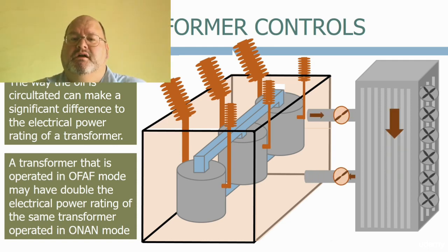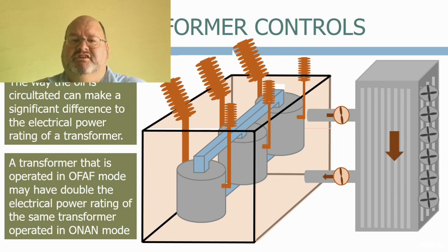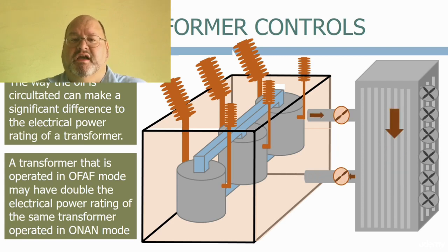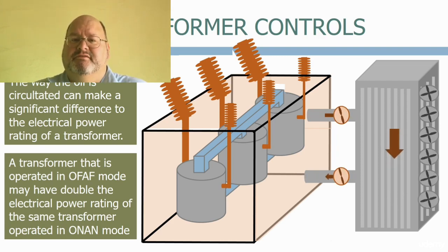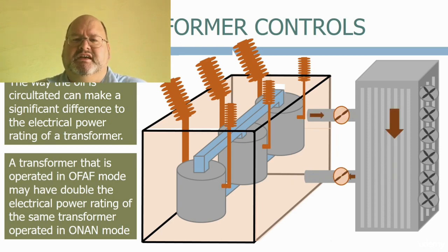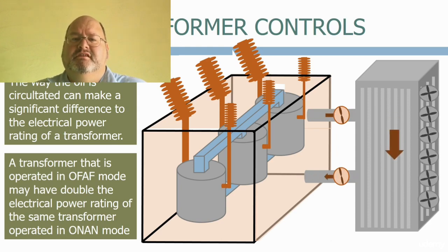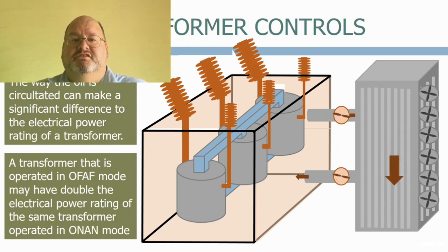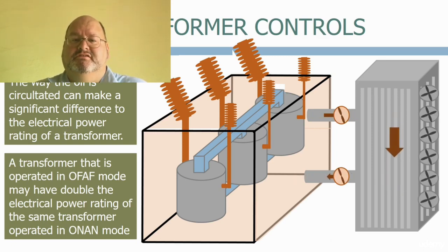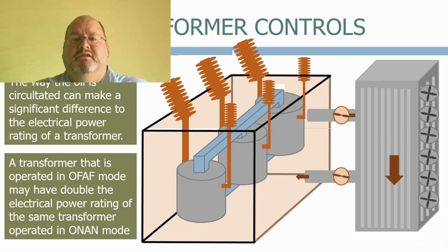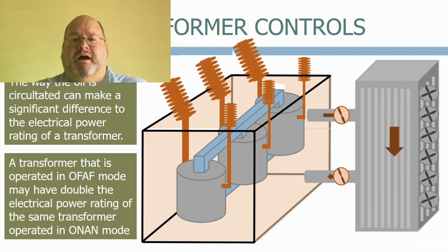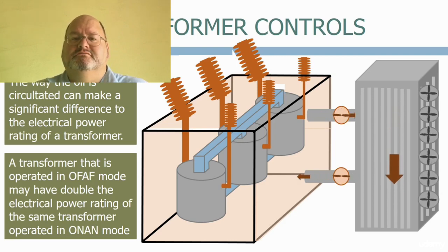Waste heat from the transformer is one of the main limiting factors in how much energy can pass through it at any one time. Transformers are some of the most efficient machines available, with most achieving 99% efficiency. But the 1% of the transformer rating that's lost through waste heat is still a substantial amount of energy, which has to be dissipated through the transformer oil and then onto the radiators and cooling fans. The cooling circuits are therefore a critical element, and losing them would mean that we can only feed half of the available power into the network, which could result in some customers losing power or having to reduce their loads.